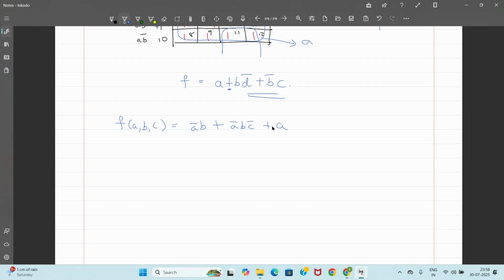In the previous videos you might have seen where I explained how to convert any given equation into standard canonical form or min-term notation form, right? That is by adding missing terms, you convert it into standard form, then write the binary notation. From that, you write the decimal values, the min-term values. Then you can solve it using K-map. So I'll just quickly explain how to do it, just a revision.